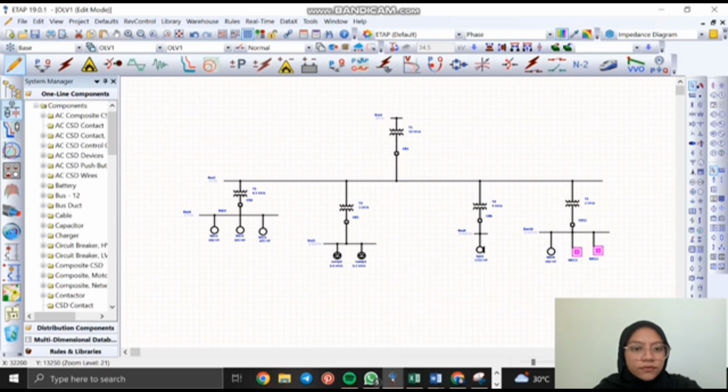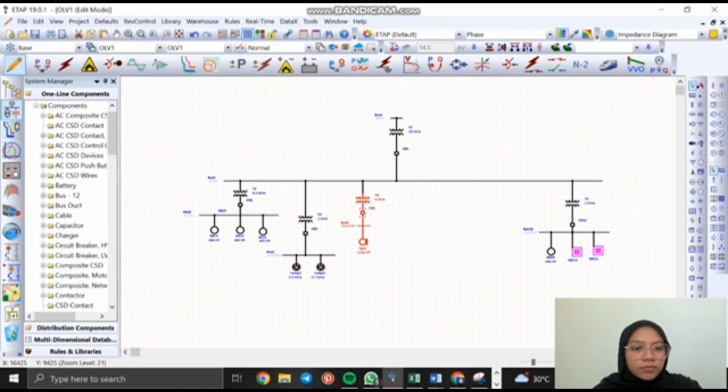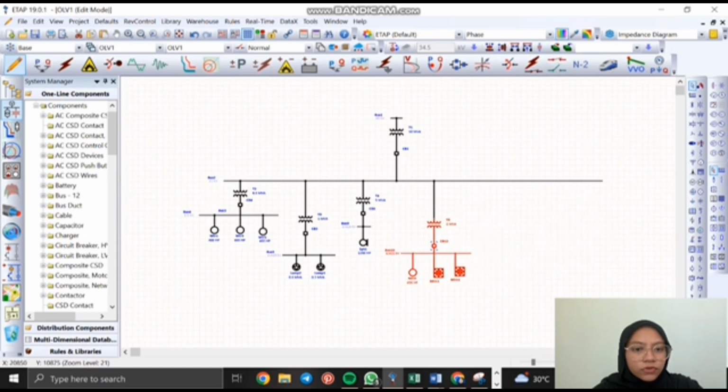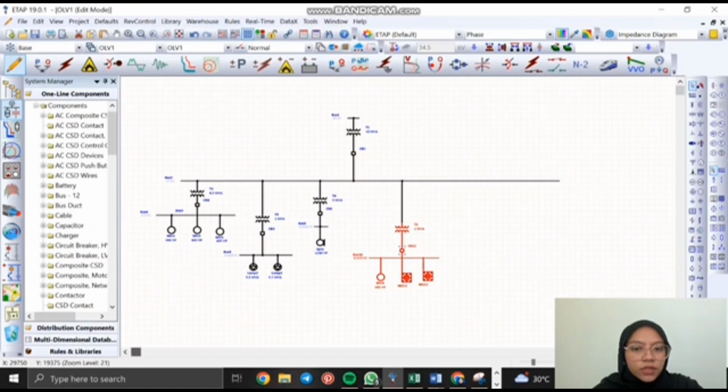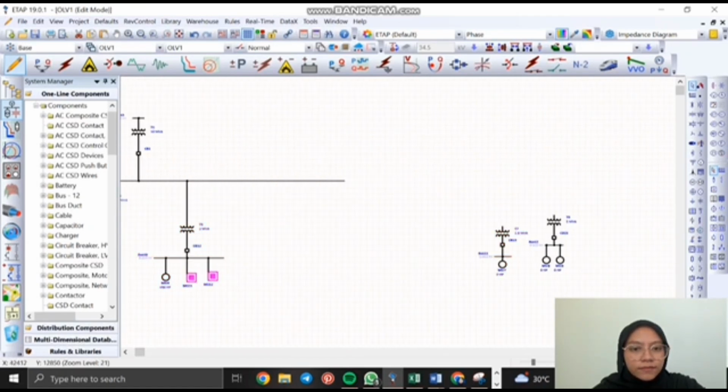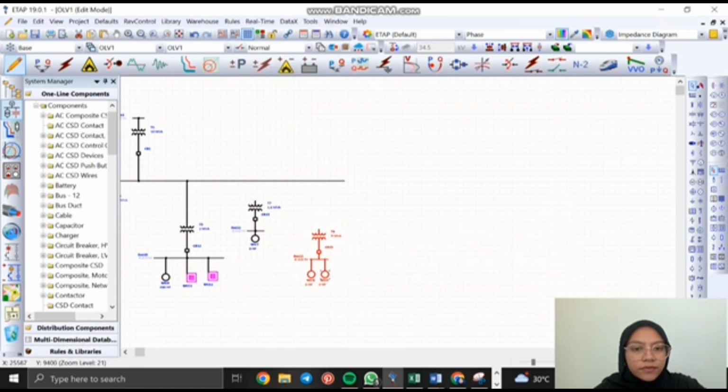lamp loads. And for T4, the transformer will step down to 0.415 volt also to supply load to the synchronous load. And lastly is the T5, which is to step down the 3 kV into 0.415 volt also, so that it can supply load to 1 motor and 2 MCC. For the next part, where there is a 60% increment of load, we have to add another 2 transformers, which are T7 and T9.